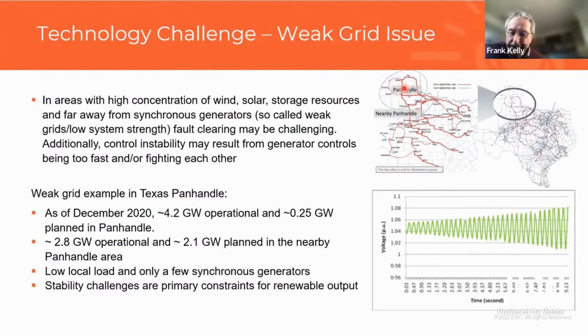Chris. Thanks, Julia. That's a really, really interesting presentation. So I was struck by your comment about the time delays for the fast but not instantaneous response. So, I mean, Yanis, I'll look to you to tell me if I've got this calculation right, but the simplest control loop with a lag, just a linear feedback, if it had a 35 millisecond delay and the gain is too high, then as it goes unstable, it'll produce an oscillation with a period of 4 times that. That's 140 milliseconds, which is, I suppose, about 7 hertz.